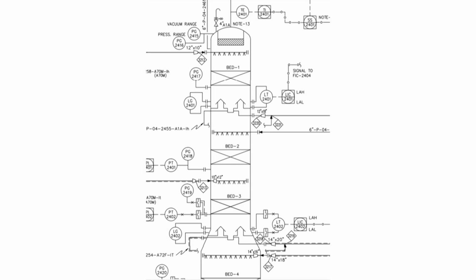But now this is a P&ID of a distillation column, and you'll see stuff like level gauges. Your P&ID may not have all these details, but at least think through, what are you measuring in a distillation column, right? The first time I did a P&ID when I was a student, you are tempted to control everything, and then you have a degrees of freedom issue, right? If you have the level in a column, you can't control both the inputs and outputs, otherwise the loops are fighting each other. But you will never discover this unless you try to make a P&ID. Right? What are the things that you should really control?